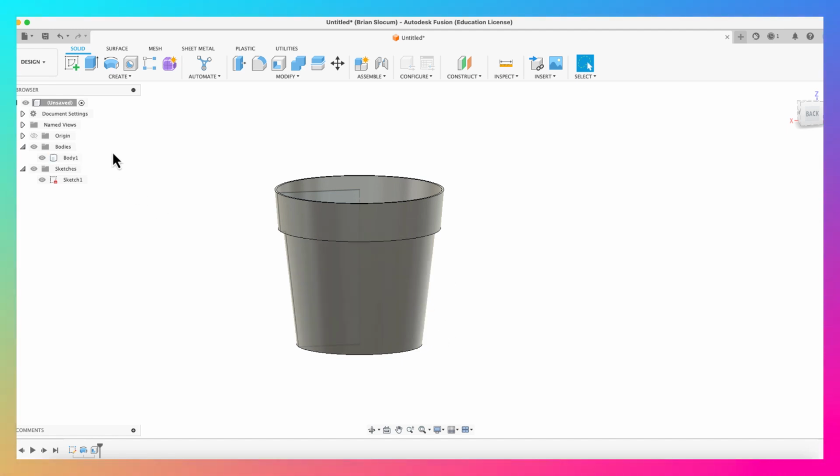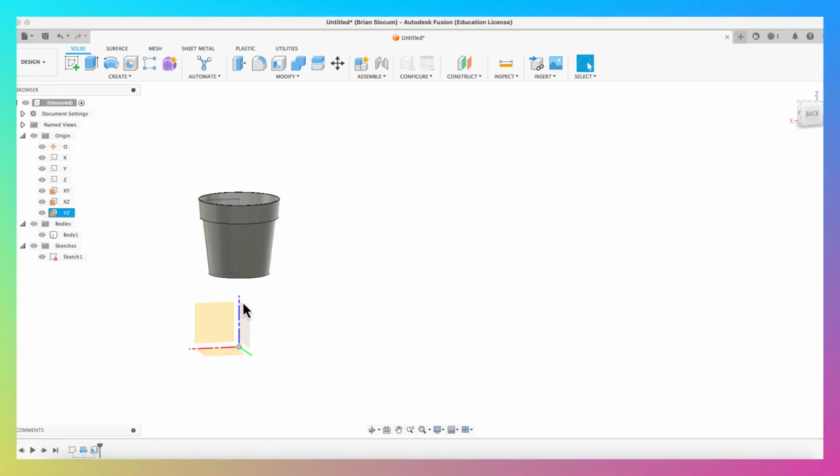I've positioned this pot. If we look at our origin bodies, and specifically the planes, you can see here's my ground plane, and what I've done is I've actually placed this bottom edge 4 inches away, because the assignment says that your plant needs to be 4 inches above your surface that it's sitting on. So my table surface is here. I wasn't explicit to say that the bottom of the pot had to be at 4 inches, or the greenery of the plant. So there's a little bit of variability in what you can choose to do. So I've just chosen this bottom lip as my ground, and so I've made that 4 inches above just to try to meet the needs of the assignment.